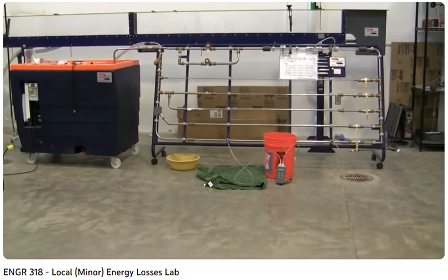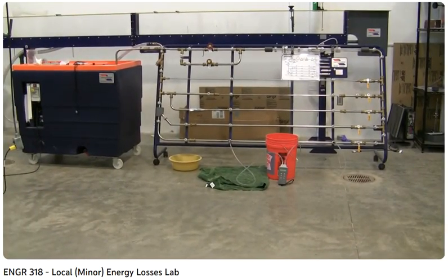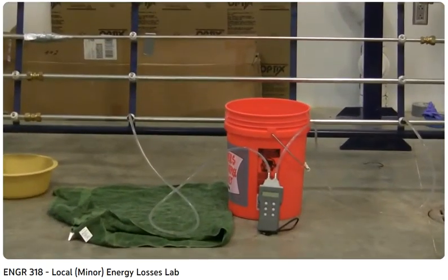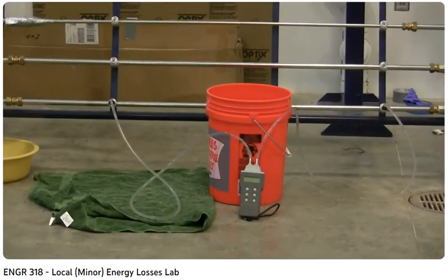A couple of auxiliary items that are shown there. You can see that there is the red bucket. The red bucket is used because it's important to purge air out of the lines that are connecting from the tap to the pressure measurement device. If little air bubbles are in that, then there can be additional fluctuation and it introduces an element of error that we want to eliminate. And so when a tap is plugged in, I'll periodically check for air in the lines, and if air is observed, then it'll be purged out of the lines into the bucket.